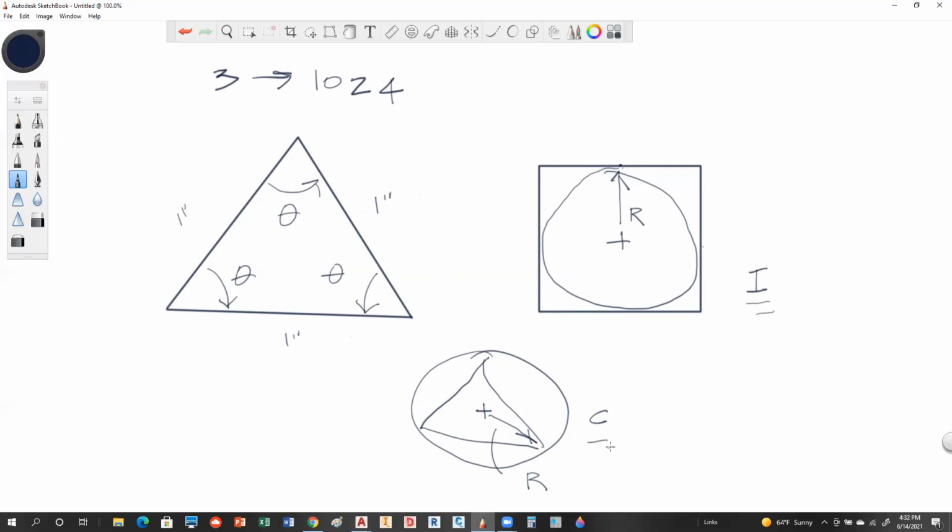So the third option is what they call edge. Edge allows you to define a distance such as this. So I could start here, and then I could give it this distance, and I could generate my polygon in that method. So there's three ways of doing polygons. Probably most people do the center point first, but this is a different option. So let's go take a look at those real quick.